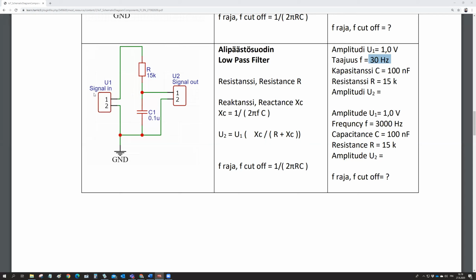Actually, what comes out if you put here a DC voltage, so a constant voltage, let's say 5 volts. If you put in 5 volts and it doesn't change at all, what happens? There is some kind of current flowing, charging this capacitance. There is no current in here, this is just the open contacts on my connector here. So current is charging this capacitance, and then it's charged to 5 volts, and the 5 volts stays here. After that, the current disappears. No current anymore when it's charged. And you have the 5 volts out here. So the 5 volts also in the output, if you connect 5 volts in here.